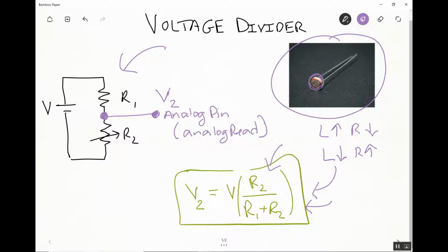Now if you did an analog read in the light, R2 would get smaller, R1 starts to matter more, and this ratio gets smaller. So V2 gets smaller. If you put that photoresistor in the light, R2 will drop, and that means V2 will get smaller. Less voltage will be utilized by the photocell. Did you figure that out?